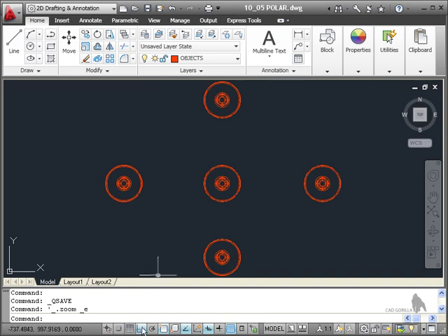I'm going to switch ortho off, and I'm going to switch on polar here. Now, you cannot have polar switched on if ortho is on. Watch. Ortho there, as soon as I click on polar, ortho switches off. Now, polar tracking is a slight variance on the ortho mode.